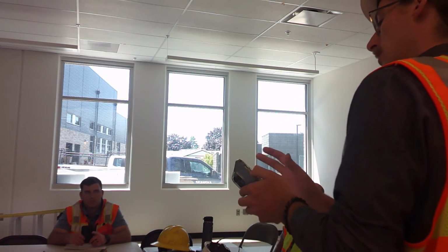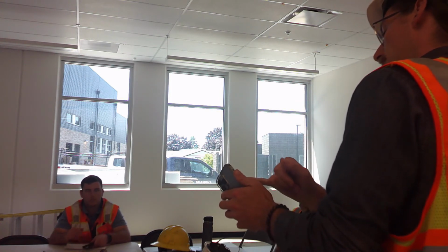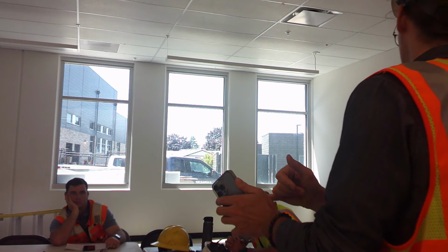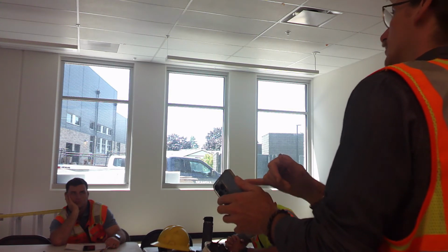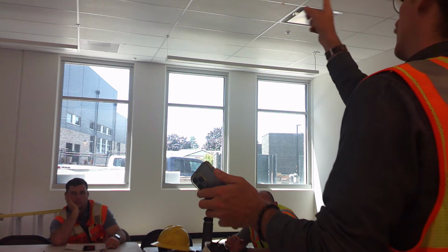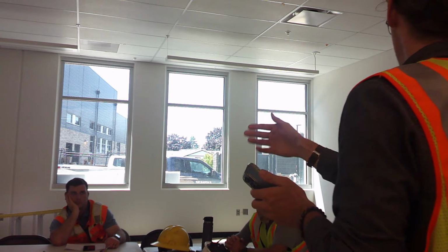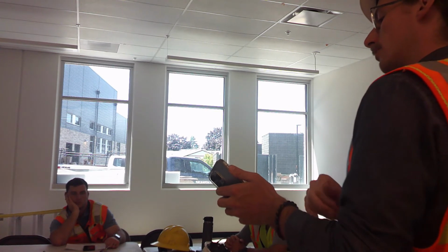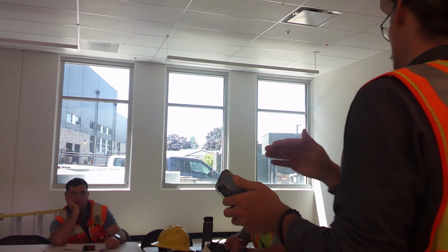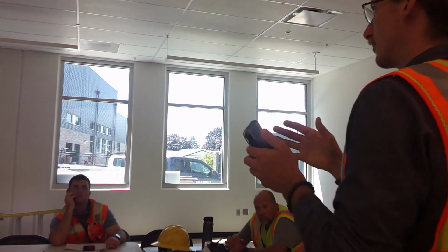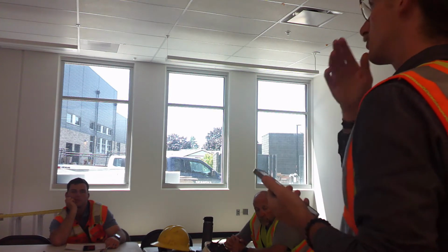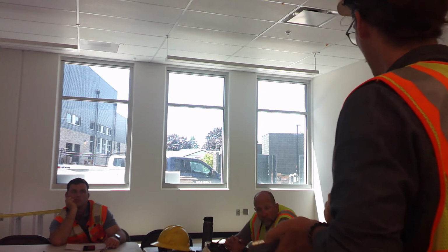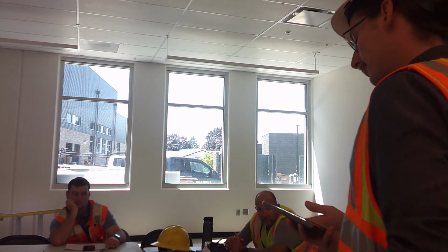You'll see in zone 2, it's set up the same way, design at 50, sensor at 120, except your at task is at 25. So that's creating a ratio at the design level and basically saying that these secondary zone lights are going to be twice as bright as the first zone. And then, same thing with that sensor value. So typically keep the sensor value the same on zone 1 and 2, so that they're following each other, twice as bright in the second zone. Anything not making sense about that? Any questions or comments?